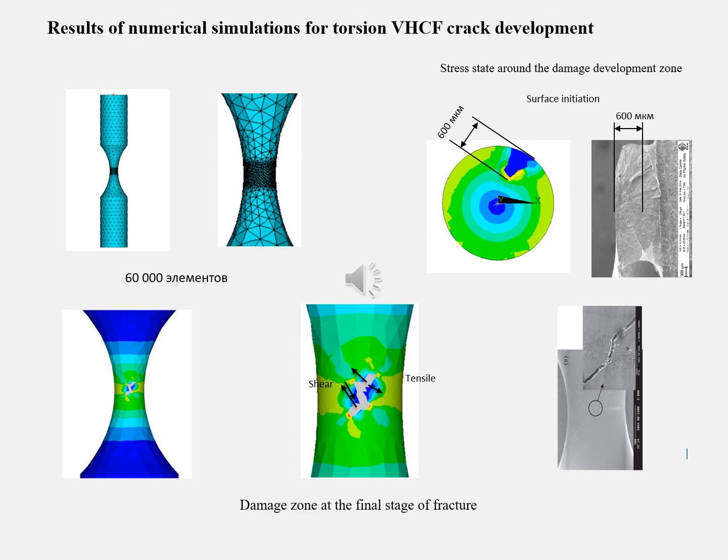On these slides, we can see the progressive damage development in this specimen that corresponds to the real fracture surface here. The depth of the crack here is limited by the size of the elements, and if we look at the fracture surface of the specimen, we have a good link between the experimental results and the numerical simulation.